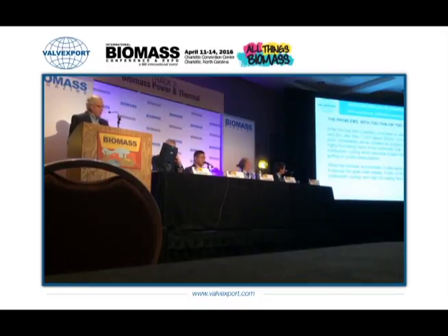When the fuel bed is partially uncovered, or when it is very thin, less than 1 inch, the ignition zone immediately above contains an unstable and highly fluctuating flame, which has been seen and recorded by some researchers. Of low luminosity, meaning it provides low radiant heat for the heat transfer, that induces combustion cycling, which becomes evident with furnace puffing or cycle pressurization.